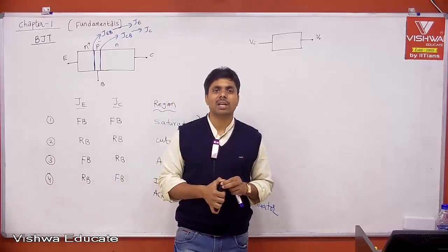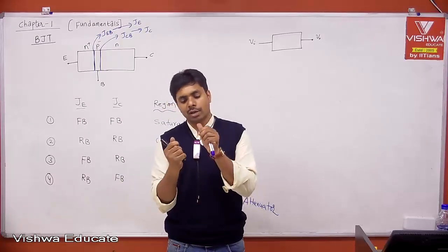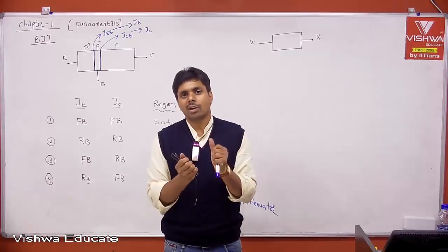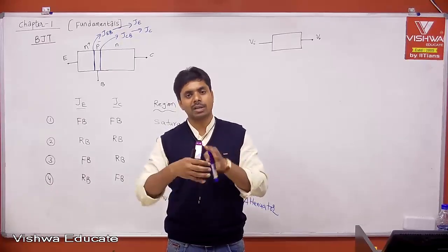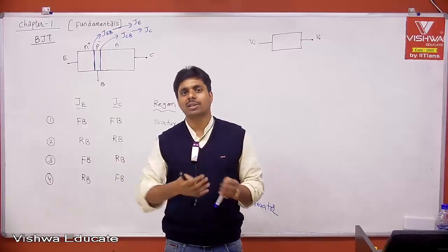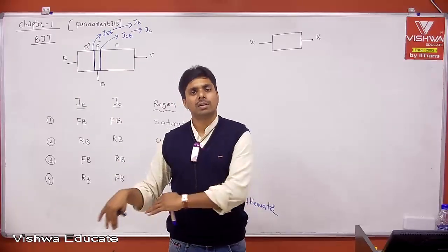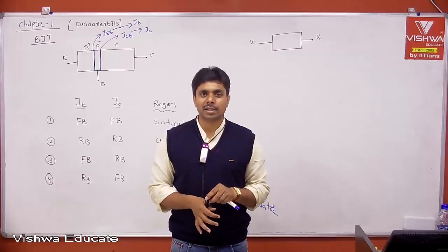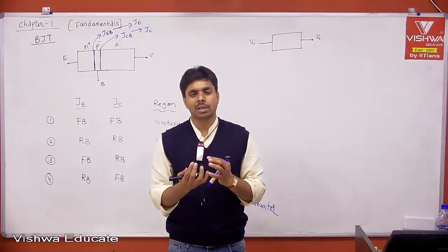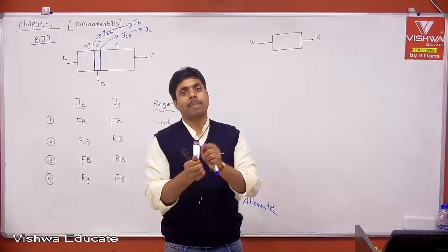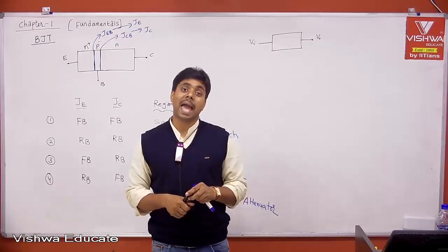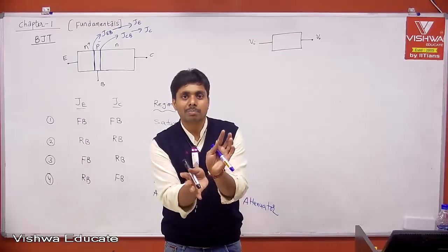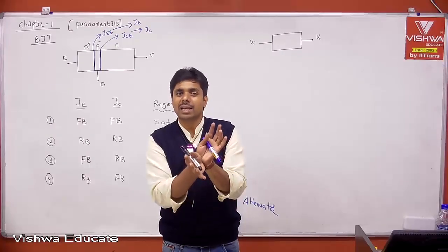A passive element is one where the amount of energy you get from the element to the outside world is zero. A resistor will not give any energy. It takes it and dissipates it as heat energy. It is a transducer converting electrical energy to heat energy, but it is not delivering any energy to the world. Similarly, an inductor takes energy, but it is not dissipating it, it is giving it back. That's why it is called a reactive element. When it is giving back, for that period it acts as an active element.